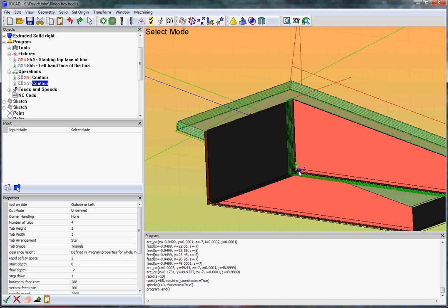So when you put some raw material down on the machine and then you touch off, you're saying, righto, CNC machine, this is the location of the 0, 0 point for G54, for example, or G55. So a fixture in JDCNC is all about marrying the graphics to the raw material on the mill itself, and it's all about those associations.